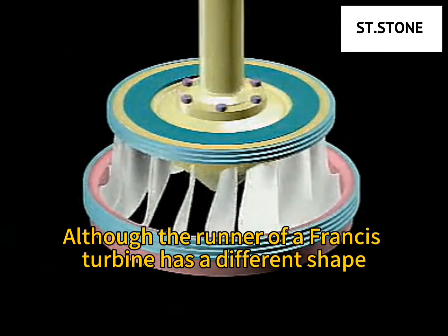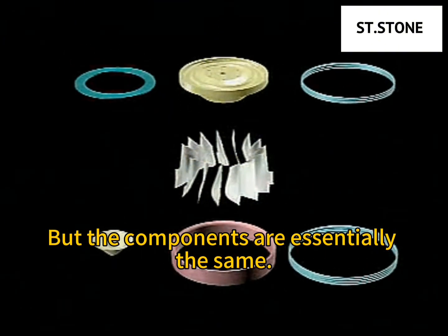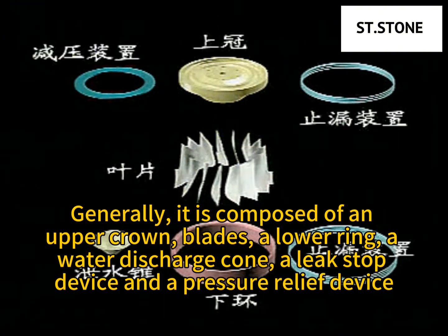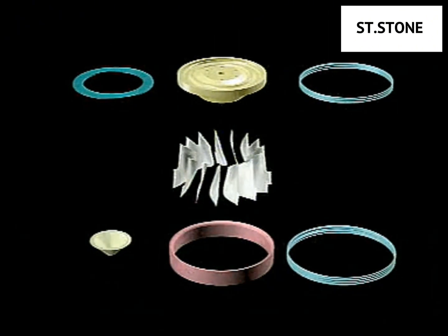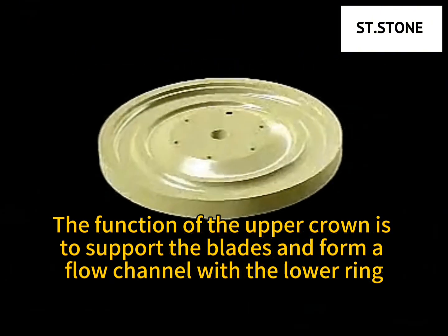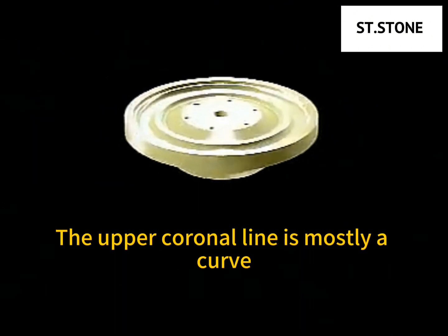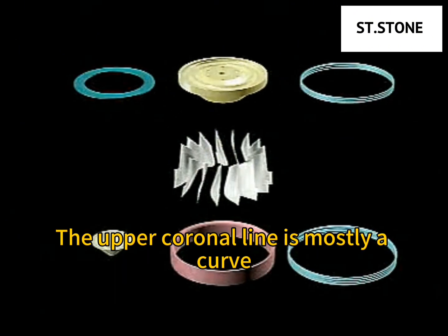Although the runner of a Francis turbine has a different shape, the components are essentially the same. Generally, it is composed of an upper crown, blades, a lower ring, a water discharge cone, a leak stop device, and a pressure relief device. The function of the upper crown is to support the blades and form a flow channel with the lower ring. It's shaped like a cone. The upper crown line is mostly a curve.